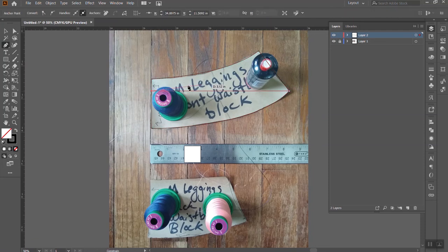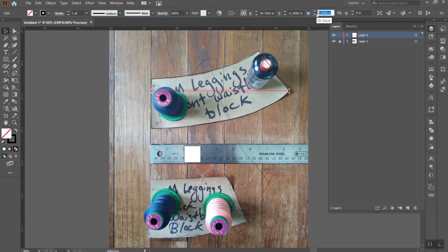So that is how we measure in Illustrator. That's at least the most straightforward way to measure. If your line is exactly horizontal or exactly vertical, you can measure using line segments, and then if you need to reference how long they are, you can click up here, 8.35.